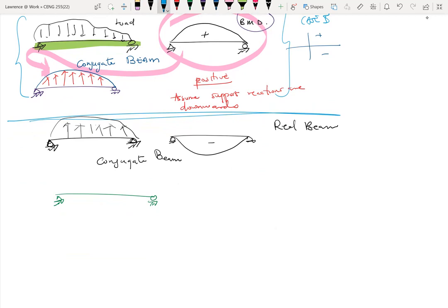So it will be downwards this way. All right. Then the direction of the load is away from the beam, right? So in the two cases, case 1 here and case 2 over here, you can see that both of them have their loads moving away from the conjugate beam. Okay, so that's what I mean by convention, let your loads move away from the conjugate beam.